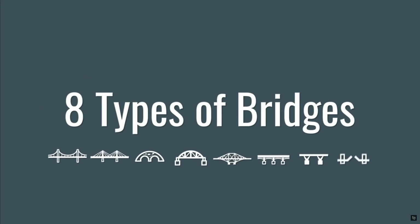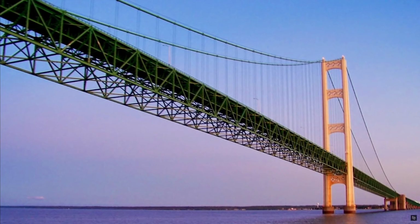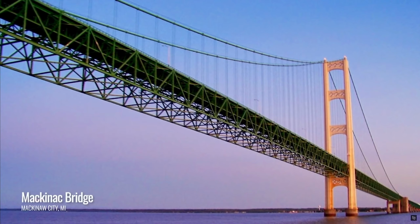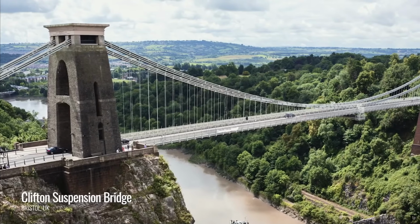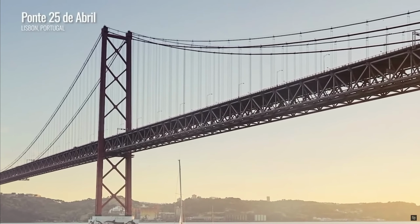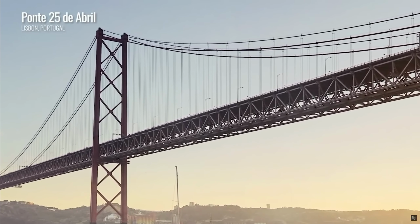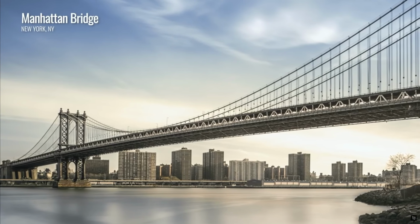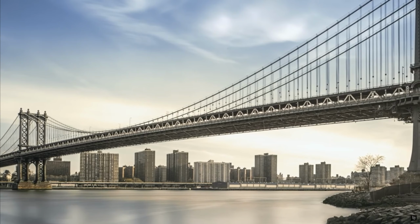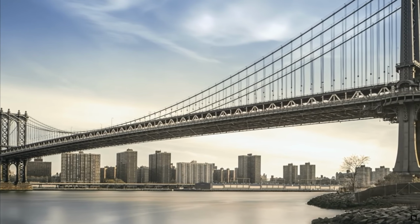So, here's a bunch of different bridge types. Suspension bridges, they are typically supports or towers connected by a draping cable. And from those draping cables on both sides of the bridge, there are vertical cables that then connect that draping cable down to the deck. And the weight of the deck is then resisted by those vertical cables in tension connected to the draping cables that then transfer the load to these towers.